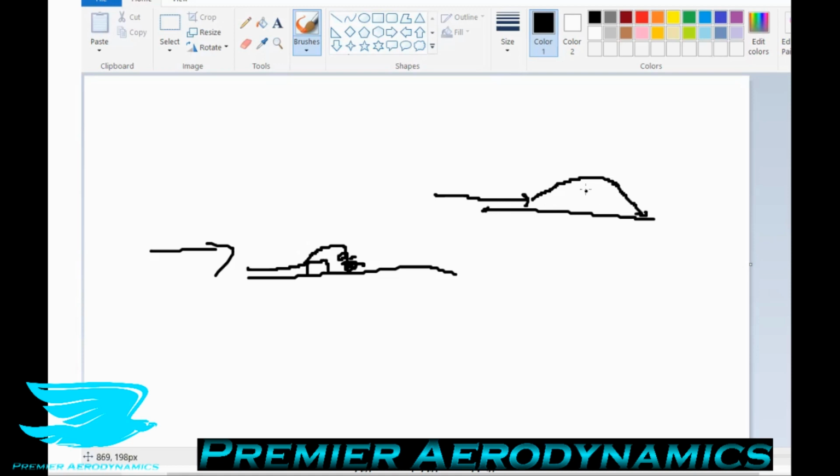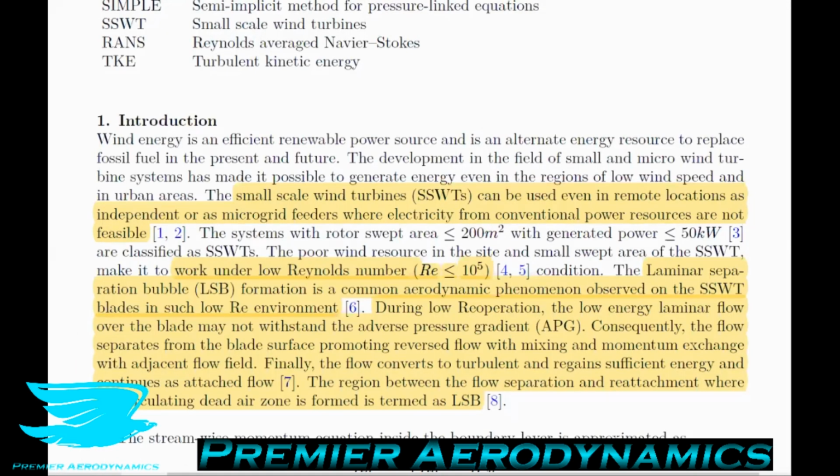Inside this bubble section we have a recirculation zone. So this bubble is now pretty much cut off from the rest of the free stream flow, and this means that this is just a dead pocket. This is potentially beneficial, but potentially detrimental to the performance of your object, depending on what you want. And we'll cover in this podcast some ways that it is detrimental.